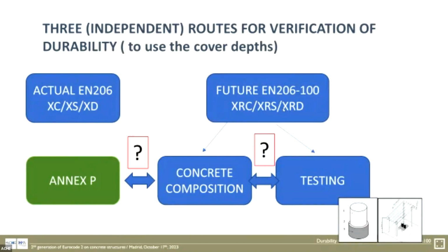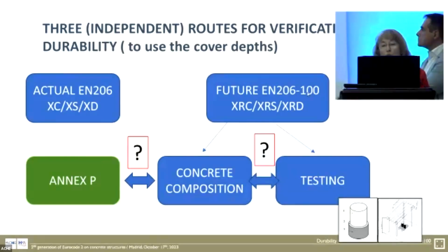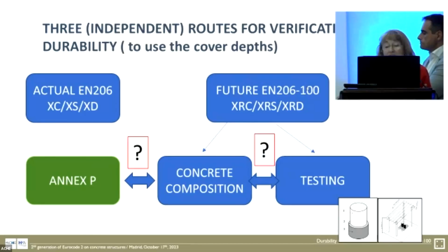And we are preparing for the future, because it has not yet been completely agreed, what is called EN 206 part 100. Why 100? In order to differentiate from part 1 and part 2, that are the most common ones. We selected 100 because it is a round value, it is nothing more than that. And there the exposure-resistant classes are being defined for carbonation, seawater, and de-icing salts.